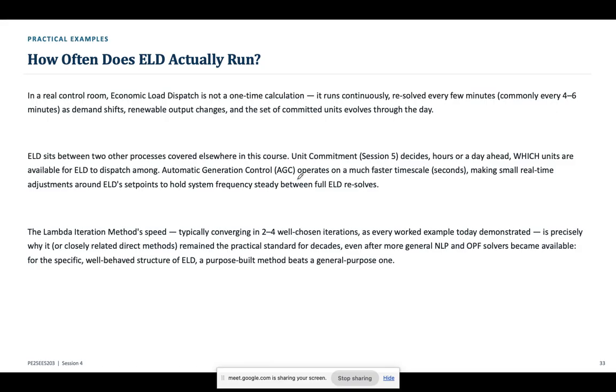When we think of Indian power sector case studies, it connects merit order to operational practices. So the central economic idea is familiar. Available generation is economically ranked according to variable costs, and the system must meet the demand while respecting technical and network constraints. So the actual control room is much more complicated than a hand calculation. Load forecast, generator declaration, renewable availability, outages, network constraints, market rules, and security requirements all influence the final schedule here.